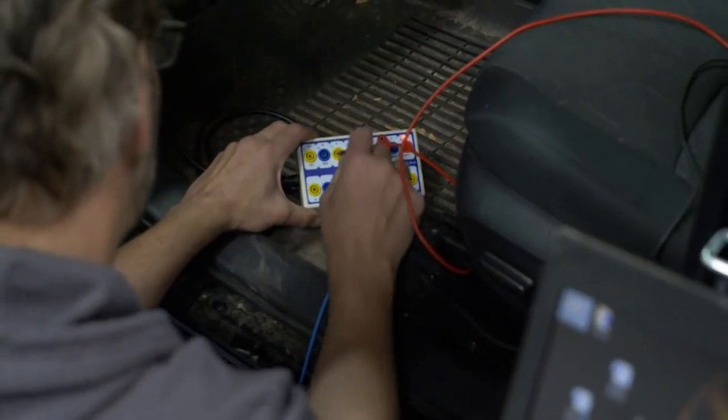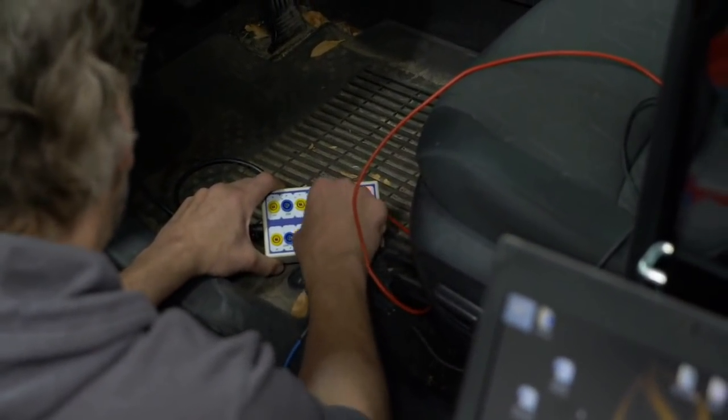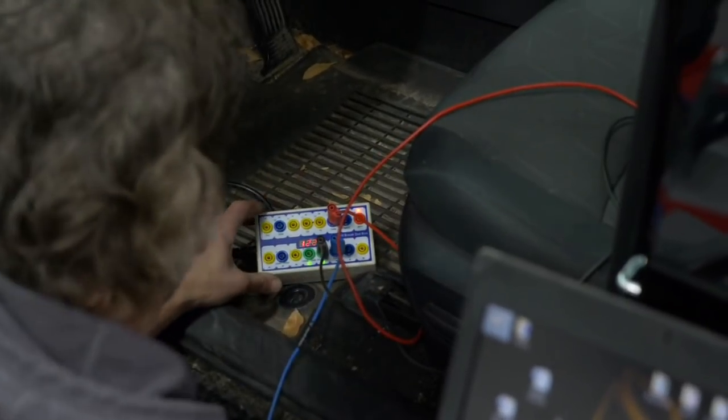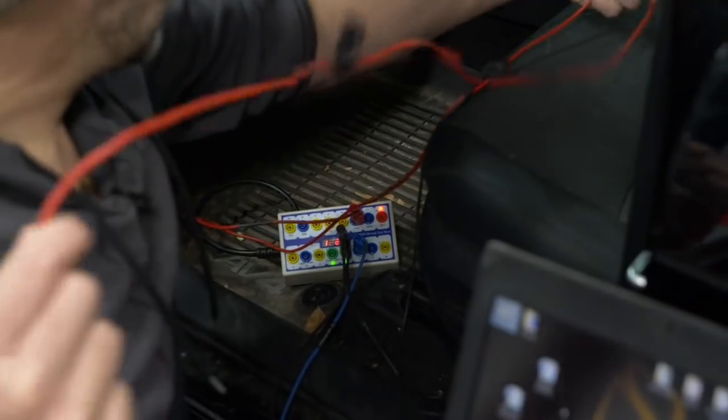You can actually use either a chassis or signal ground. I think I'm just going to go ahead and use the signal ground, assuming there will be less noise than everything else being on the chassis. Like that. Now I can connect my channels up to my PicoScope.